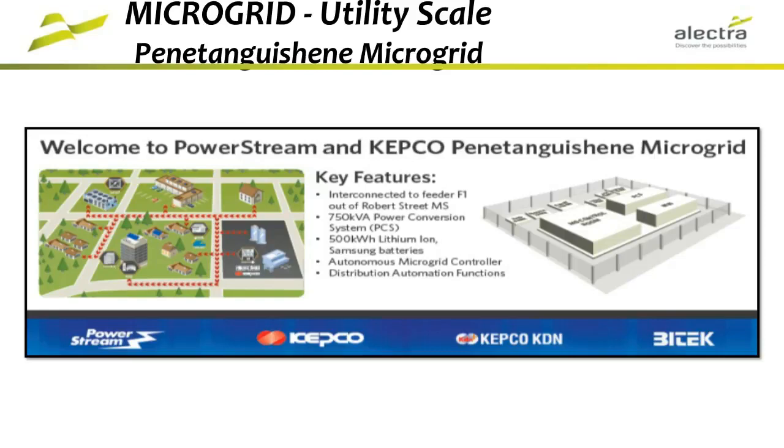Typical issues with a community or a substation at the end of a long line: voltage issues, outage problems. So as opposed to going for a traditional utility asset, we decided to reinforce the station with a bulk solution. There is an autonomous microgrid controller that right now is visible through our SCADA system in our operations room and is operating as essentially a distribution asset. We are evaluating a number of discrete use cases.